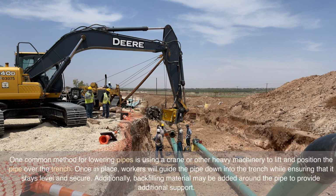One common method for lowering pipes is using a crane or other heavy machinery to lift and position the pipe over the trench. Once in place, workers will guide the pipe down into the trench while ensuring that it stays level and secure. Additionally, backfilling material may be added around the pipe to provide additional support.